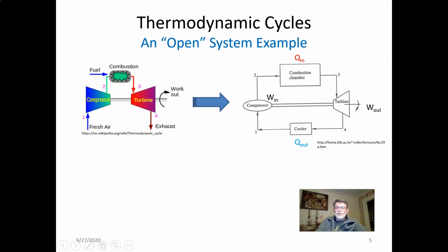Gas turbines are composed of three main components. You've got the compressor here, the combustion chamber, and the power turbine here. In the compressor section, air is drawn in at the air intake here, and it's compressed, generally about 30 times the atmospheric pressure, so it's a very good ratio.